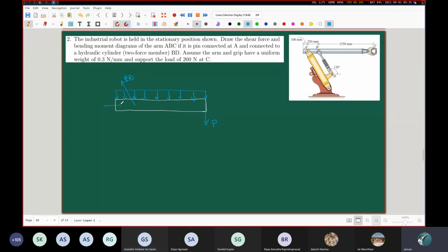Let me take it to be AH and AV. So A vertical and A horizontal. What do you think the A horizontal should be equal to? The horizontal component of FBD, so FBD cos theta. The only chance for AH to be balanced is by the horizontal component of this BD force from the two-force member BD. And it's a good situation for us because this angle and all the geometry and everything is available to us.